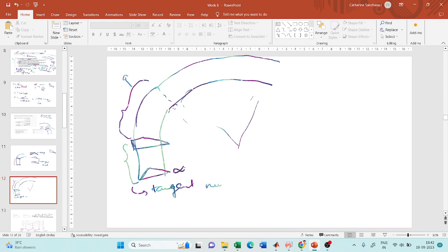Here the radius will be infinity and here it will have a radius of R. So you have to provide a gradual transition. Here the centrifugal force will be zero and here it will have a centrifugal force, right? It will be pulled outwards. So that also should be gradually introduced.